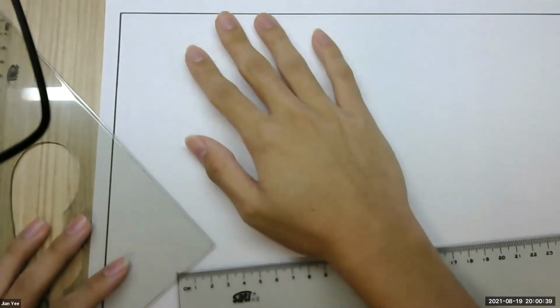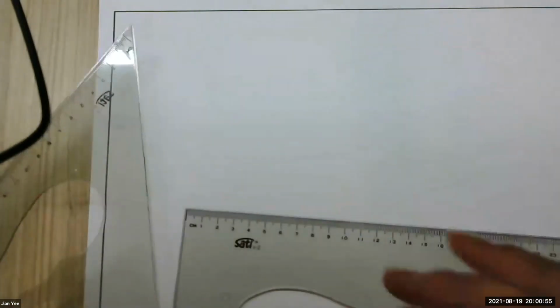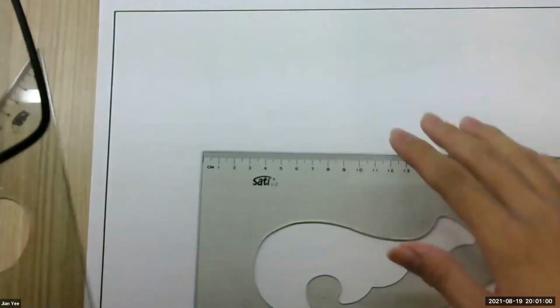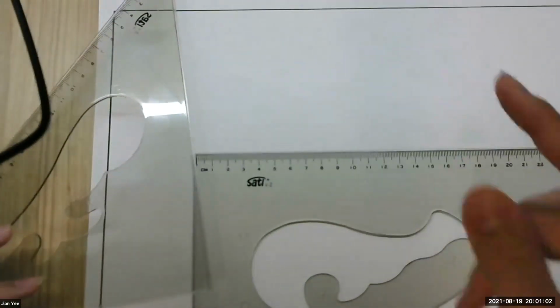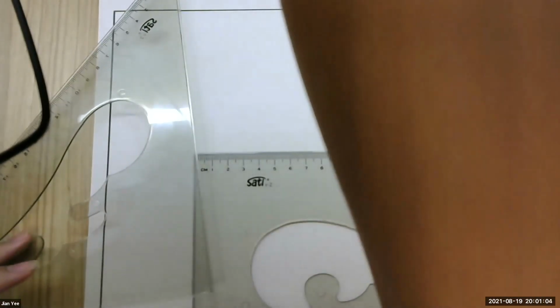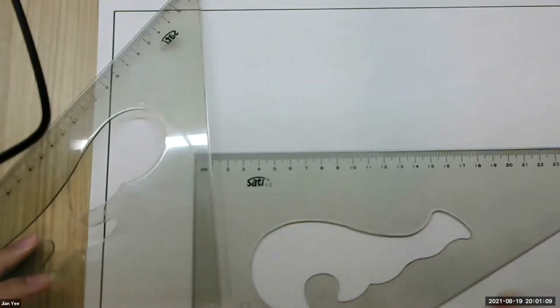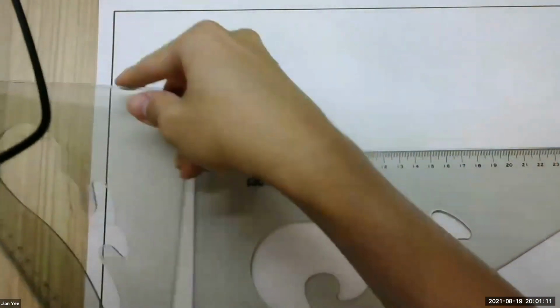So in this case for M1 question 1, it's a third angle or first angle? It's a first angle. So I'll start with the side first. Some tutors specify where you start on, so I'm not going to butt into that. So for the height of question 1, the shape is 60. Normally what you do is you draw the outline first. So go here.